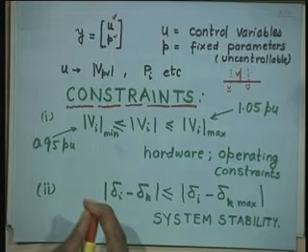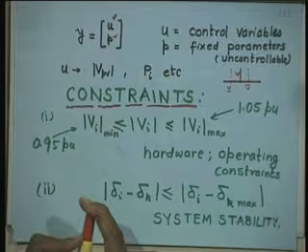But in India, what is the voltage variation? Plus minus infinity. What is the meaning of that? A 220 volt supply can be as low as 170 volts, can be as high as 270 volts. If you go and see a 60 watt bulb, it is giving you lumens of a 40 watt, because the voltage is low. Low voltage problem is very prevalent in this country.